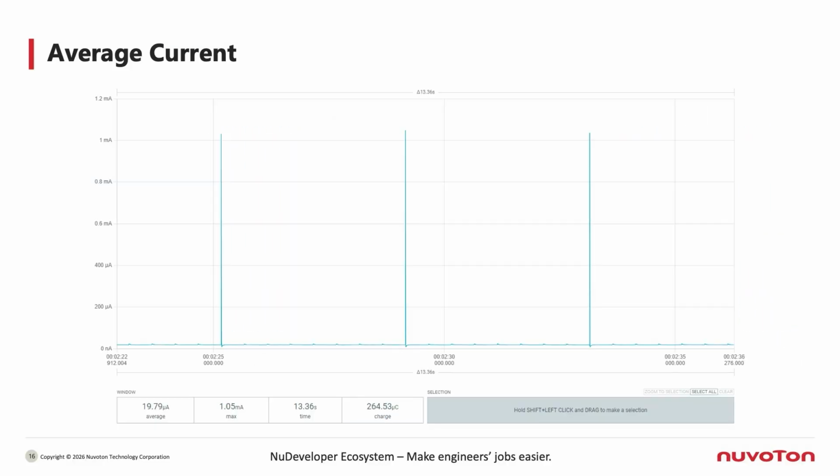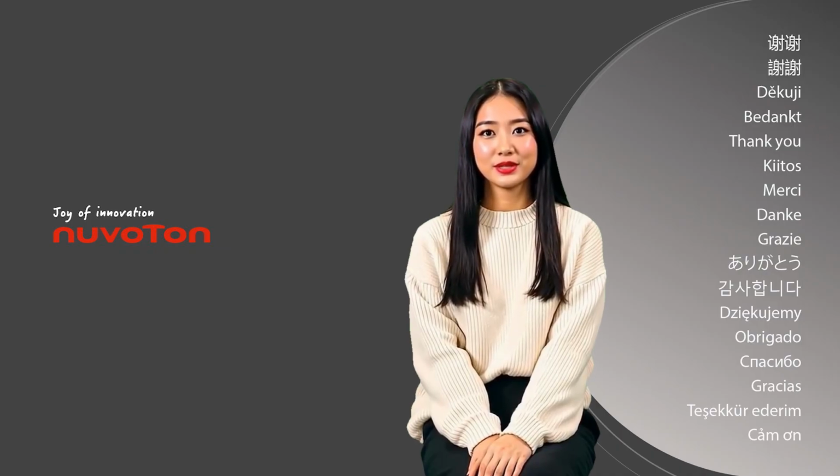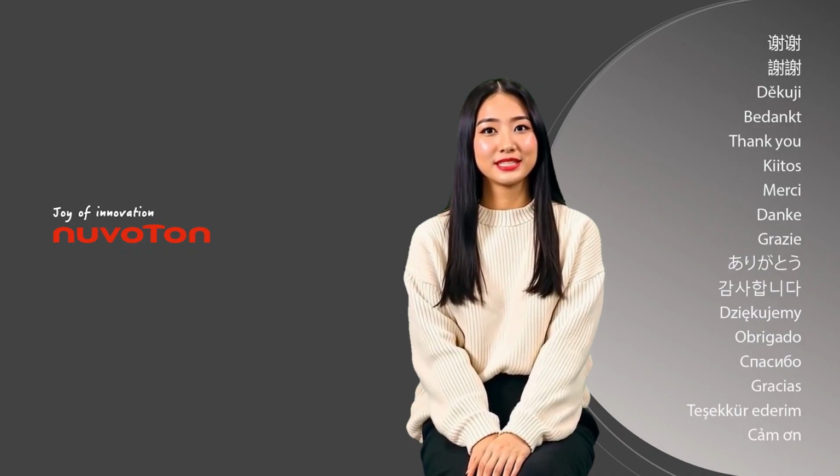Following the program flow, we can actually see the system's behavior directly when measuring the current. The current peaks correspond to the CPU being woken up once after the low-power PDMA finishes transferring all 48 data points, and then it goes back into power down mode. You can try changing the length of the data transfer to see how it affects the low-power behavior. That wraps up our example program demonstration for the low-power timer UART in transmit mode.